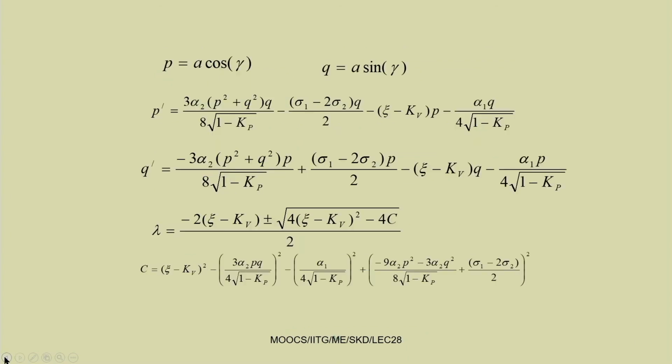In this way, we know how to derive the equation of motion. Particularly in the second case, we derived the equation using the energy method and, subsequently, a first order, one mode approximation. You have seen this equation, and we have used the control system here also. Here we used the parameters E and I. E is the Young's modulus, which is constant for an elastic material. Later we will take a viscoelastic material, where the property will be different. For viscoelastic material, E cannot be a real number; it will be a complex number.